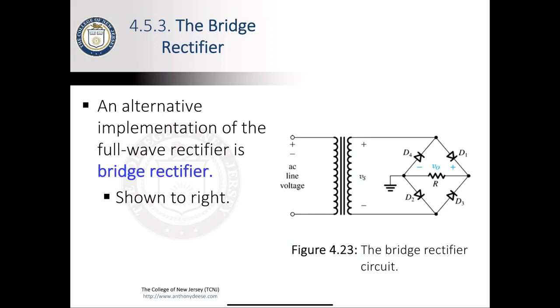Okay, now, moving on. There are other rectifier configurations, and another is called the bridge rectifier. Now, the main advantage of the bridge rectifier is that we don't really need this transformer right here. I mean, it's showing a transformer for electrical isolation, but you'll see here in a second that it's not integral to the way that the rectifier behaves.